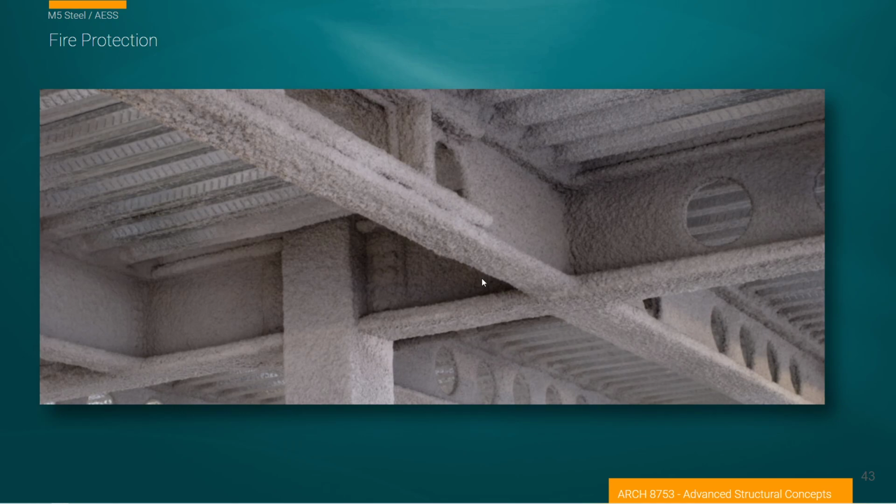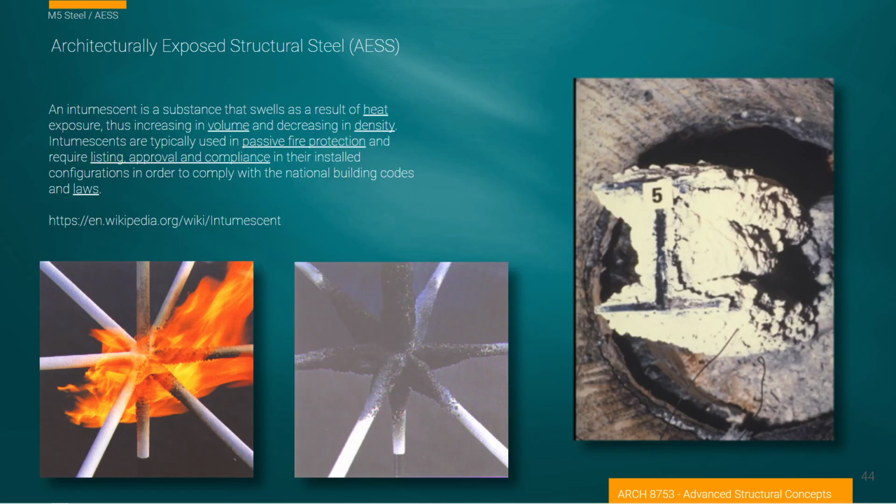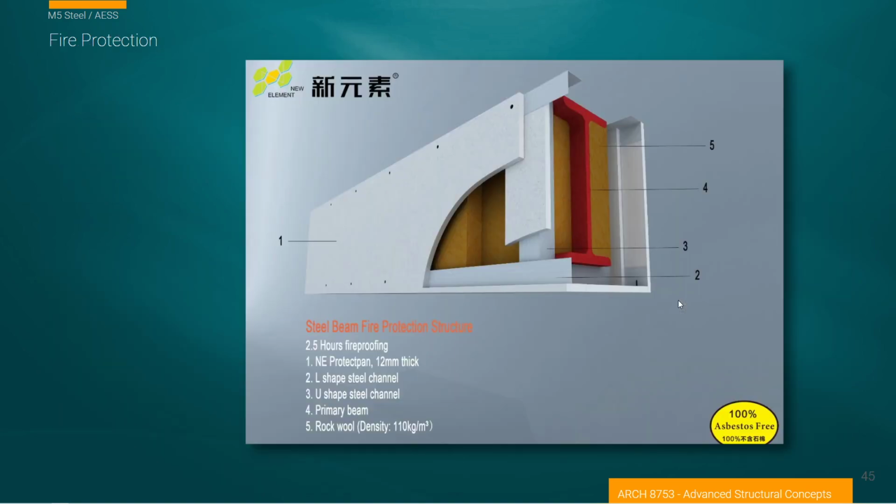and some of the treatments to prevent that issue, fire issues within the structure that would deteriorate the structural performance, and that are insulation over the metal as a form of fireproofing to delay the effects of heat. We have painting systems, intumescent systems that actually look smooth until they are exposed to heat, and then they create a kind of a foamed surface that increases the kind of thermal resistance and works to protect the beam.